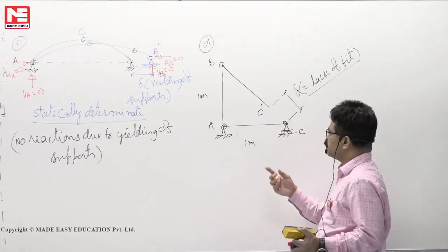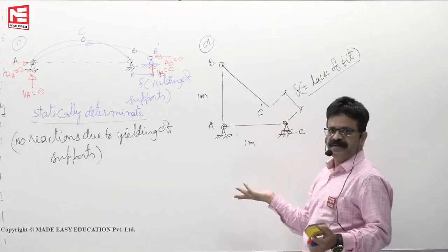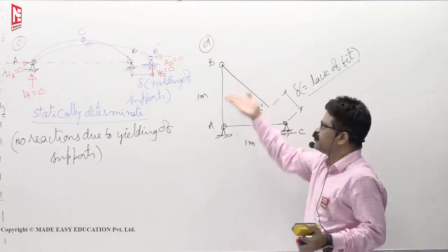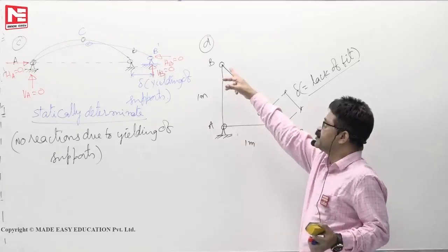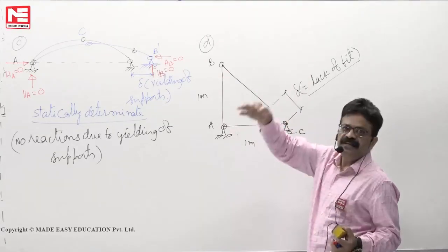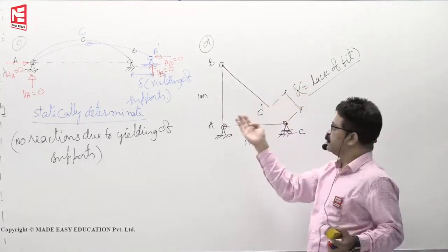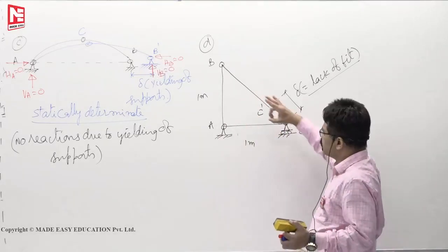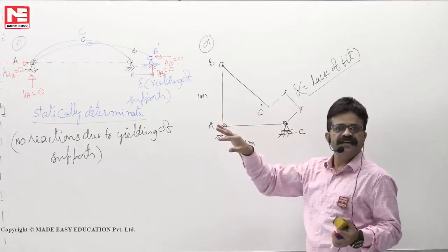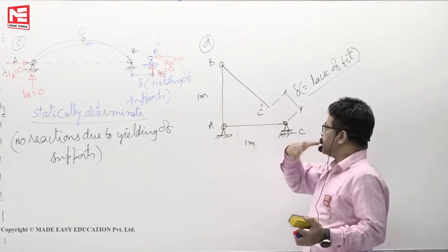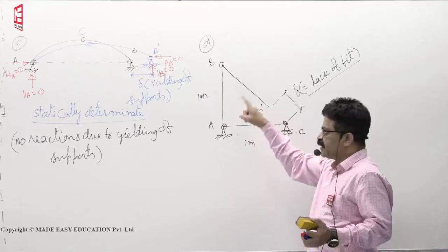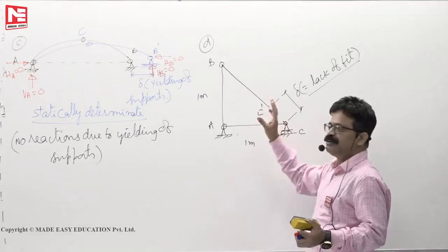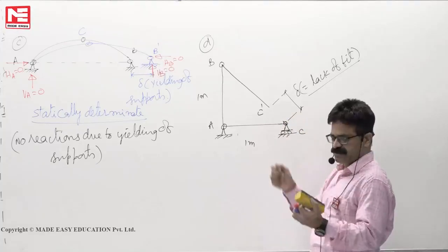In such cases, everybody will just pull it and bolt it. When I am pulling and bolting it, will forces develop? We see this joint is now in air. Triangulation didn't form. So as it is in this case, it is a mechanism. If you tap like this, it will fall, rotate 180 degrees also. Triangle also didn't form. So it is a mechanism. So easily, without developing any stress, I can pull and bolt it.